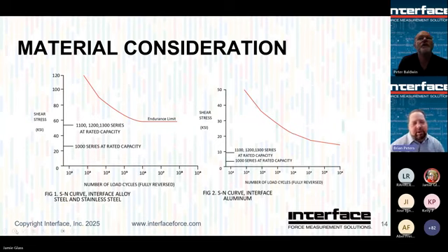Our fatigue rated load cells, we target them to be operating much lower, around 25 to 30, to ensure, again, that it's well below the endurance limit, okay? That endurance limit on the right side of the left graph, as long as stress levels stay below that, you have essentially infinite life in the material, right? So that's the goal. Want to make sure to stay below it.